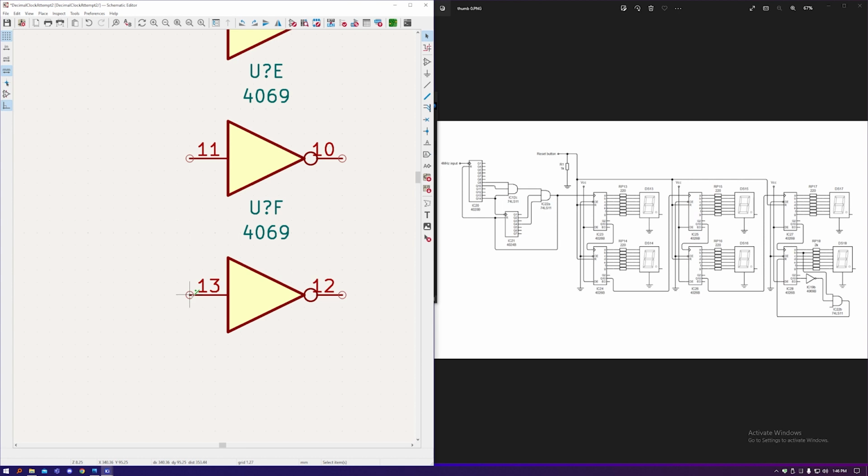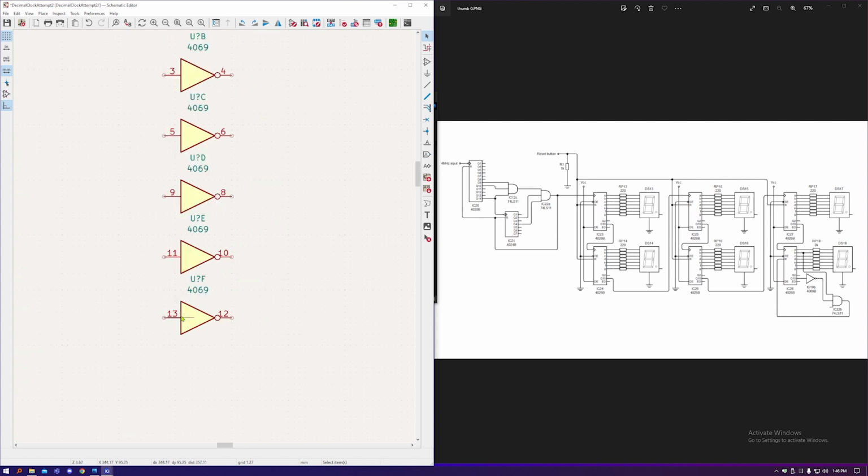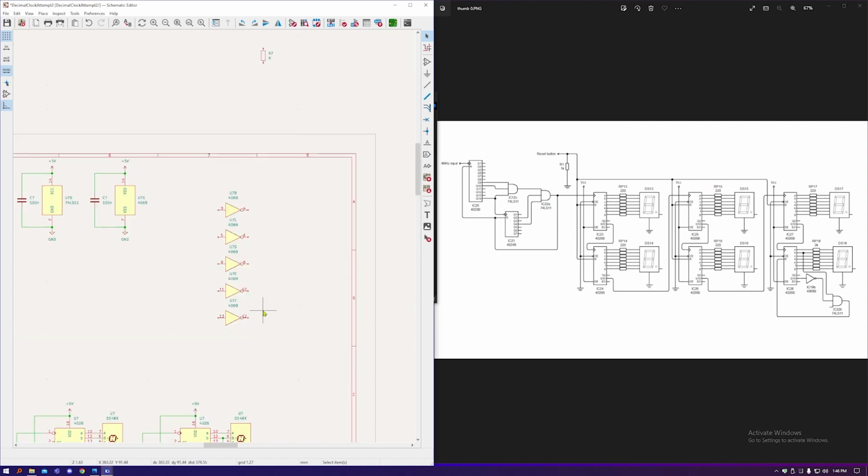So I've had a high-speed version of the 4069 before, just on a breadboard. Plug it in. If all the inputs are grounded, it draws 0 current, as it should, as in less than a milliamp. If you leave all the inputs floating, you can have this chip just on its own on the breadboard drawing 20 or 30 milliamps, because every inverter is oscillating as fast as it can at many megahertz, and we don't want that.